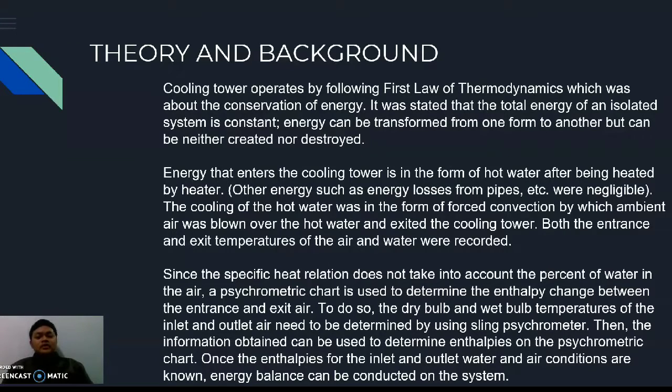Energy that enters the cooling tower is in the form of hot water after being heated by the heater, where the other energy sources are negligible. The cooling of the hot water is by forced convection, in which ambient air is blown over the hot water and exits the cooling tower.